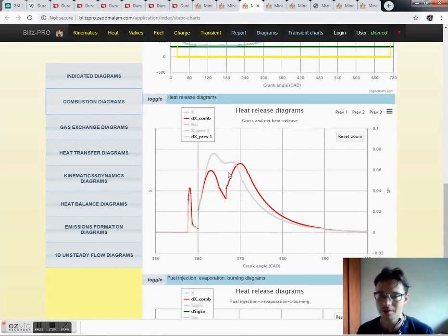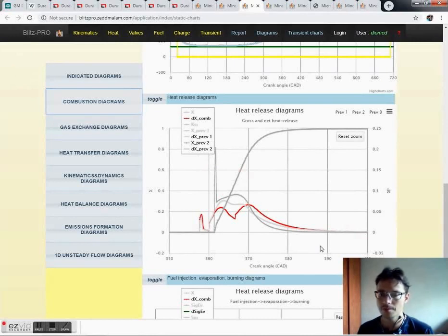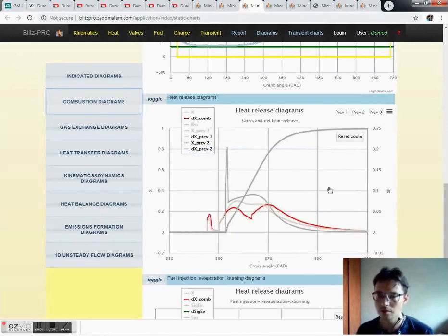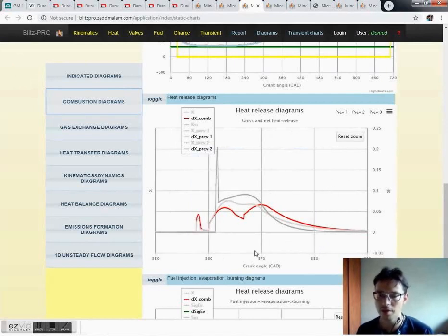And that helps to drop this maximum pressure. And when we compare it with the single fuel injection, we can really see this difference in combustion patterns. We can see this enormous first peak of combustion speed because of the fast combustion of fuel evaporated during the ignition delay. So that's it.